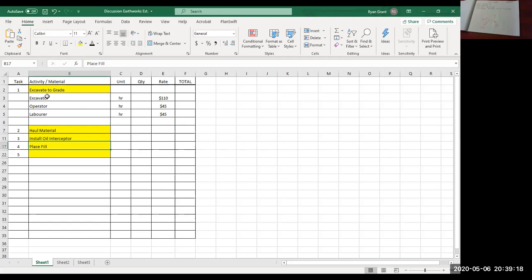So we've dug, we've hauled off the spoil, we've put the concrete box in, that's going to be in our fill quantity. You're right, Ivan, we do need 100 millimeters minimum of gravel underneath. We're going to say that volume is in our place fill volume. So we're not going to separate it into 2 items. Good question though. So what is last?